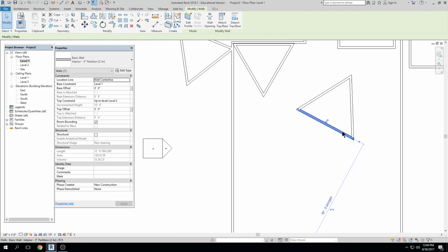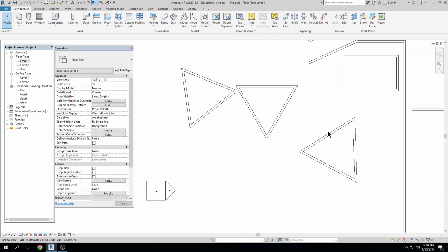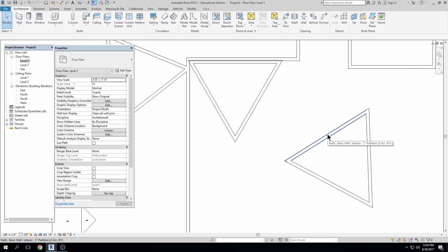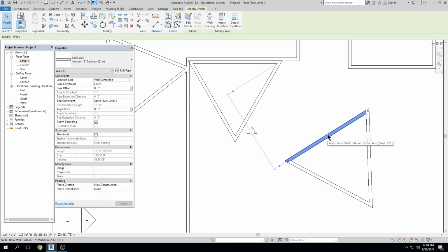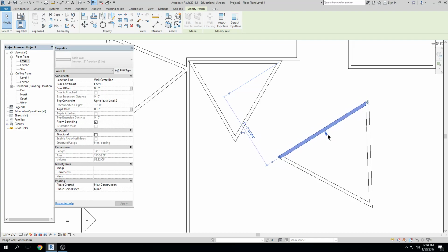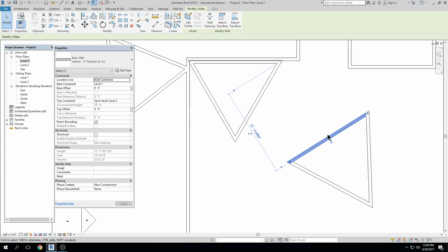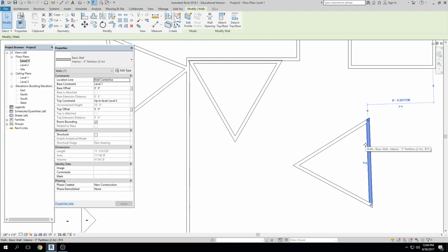right? Here's a couple of things that will help us modify that are a little different than in AutoCAD. Revit has a nudge option and it also has a drag, okay? If I click on an object and I want to move it, I can use the move command. I can use the temporary dimensions to change it, but I can also use a nudge option, which is on the keyboard, the up and down arrows and the side to side arrows, right? Click, click, click, click with my arrows. I can move things. I actually wish AutoCAD had this option. Nudge would be really helpful in AutoCAD just to move things a tiny bit, right? But I can make things bigger, smaller, nudging them.